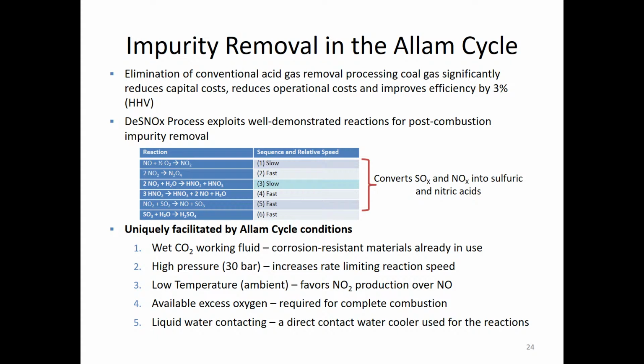This system has been verified in pilot plant conditions in the US, the UK, and Australia, where there's a lot of interest in this process, and it works perfectly. In fact, the system will work down to a pressure of about 10 bars. So our pressure of 30 bars with a residence time in the direct contact cooler of just a few seconds is an excellent solution. Next slide.